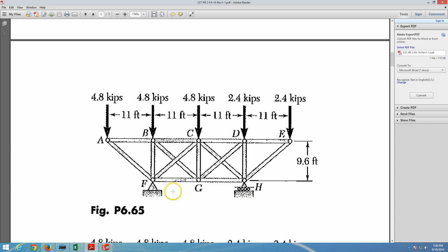You will start making this model on the front plane in SolidWorks by making the linear 2D sketch. After that you will go into welding structural members and build out the frame using the structural members, followed by the simulation setup. So let's now start SolidWorks and let's start building this piece.